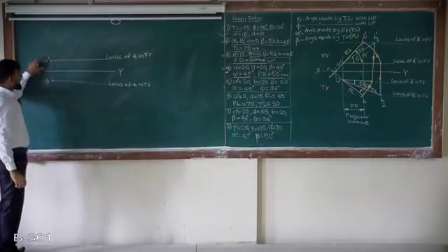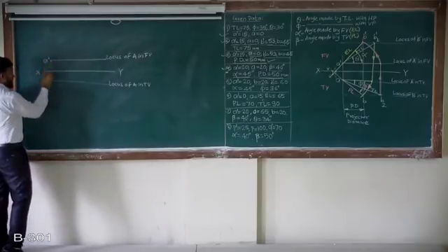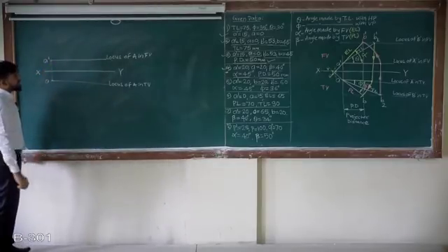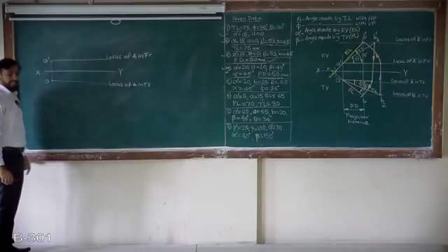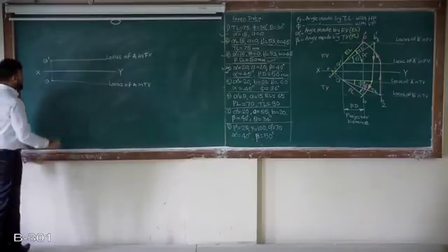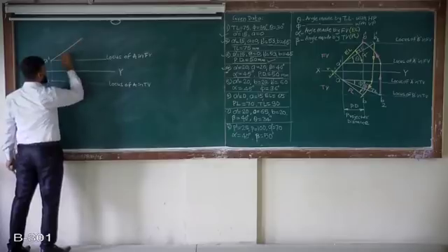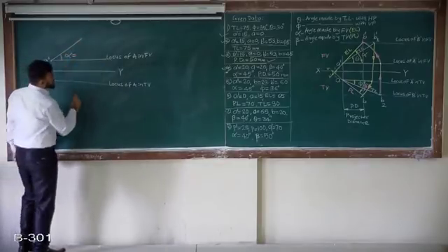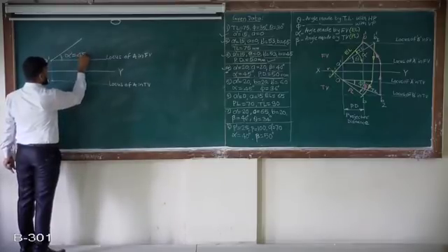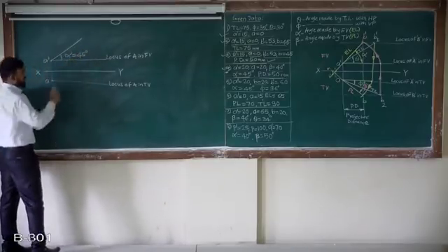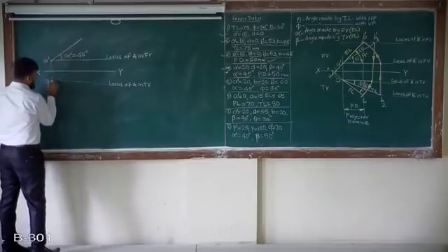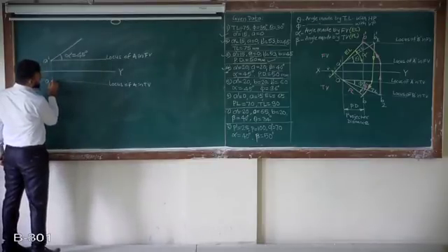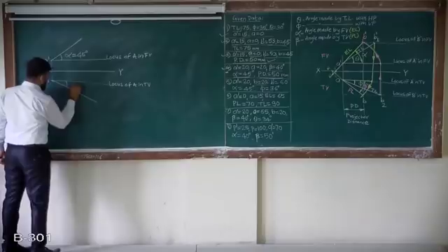So I plotted A dash A 20 mm above and below. Next, I know the apparent angles in front and top view. So I will mark the alpha angle at point A, which is given as 45 degree, because this is the angle made by the front view. So I need to draw it here. Then the beta angle is given as 40 degree.